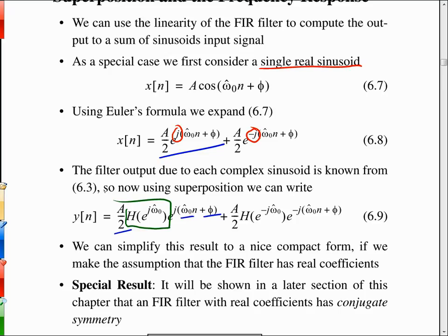This is a fundamental concept for all electrical engineers, in my opinion, whether it's discrete time or continuous time. A sinusoid goes into a linear time invariant system, and it comes back out again just as it went in, as the blue underlined pieces of the equation show, plus there's an additional term that's been added or multiplied in, and that's the frequency response at that frequency. So it picks up the gain and the phase associated with H of e to the j omega, which is the gain, amplitude response, and the phase shift that the system imparts to that signal.